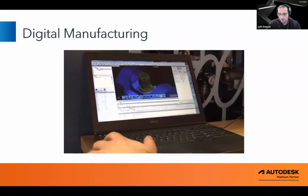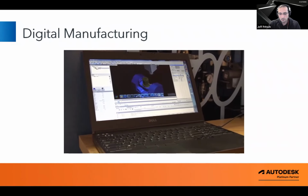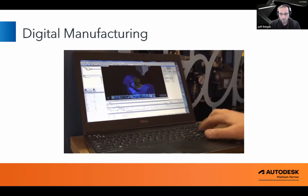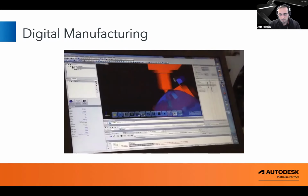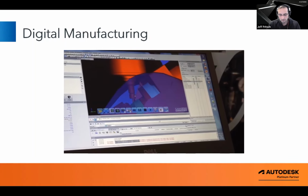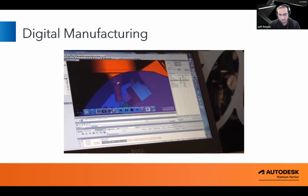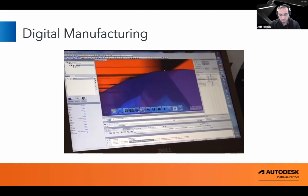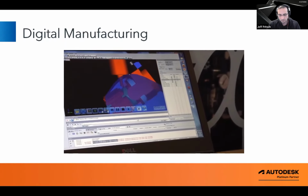So here's the machine simulation. And I have different proximity warnings I can set for it. So if I tell it I want it to warn me if I get within half an inch of crashing into anything else, and I go ahead and run this simulation. And so looking in here, we can see there's a lot of stuff going on where it gets really close. We've got the tool holder right here getting very close to the fixture and all this stuff. But the one that's really scary is right here. We have the body of the spindle getting extremely close to the trunnion table here. We're really right up there. So I have a half an inch proximity warning set right now, and it errored out.